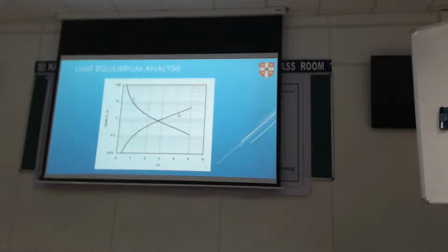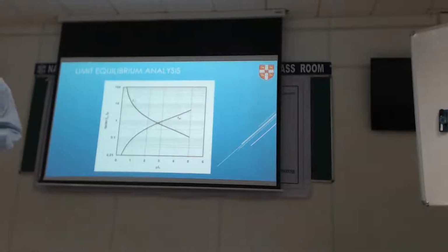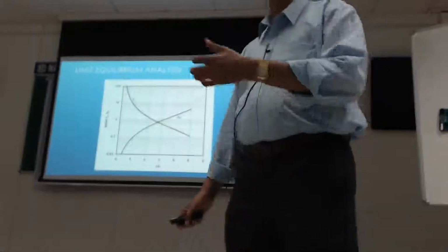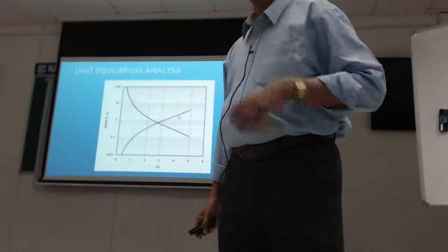Because most of the experimental work before this happened with just piles and pile cap, very lightly loaded pile cap. Nobody was worrying or considering the fact that the pile cap is there to actually carry some vertical load. People ignore the structure, and that's a problem, in the sense that it affects how the pile group works. It's not that we are so enamored with the structure on the top, but if it's going to make a difference to how the pile foundations are behaving, we need to know that.